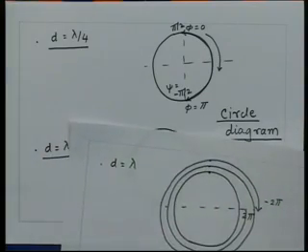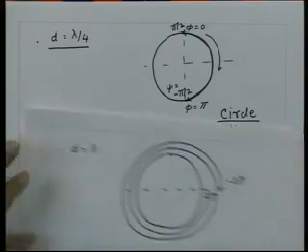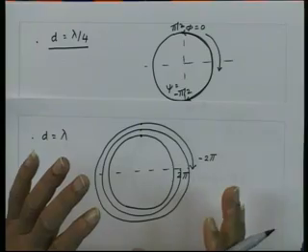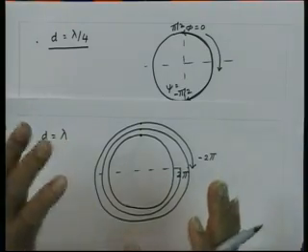Circle diagram essentially is the visualization of the roots of the polynomial on the unit circle or in general on the complex z plane, to see whether these nulls would correspond to the physical nulls in the radiation pattern or not. Once you understand this, then synthesizing an array which is specified by their nulls is very straightforward.